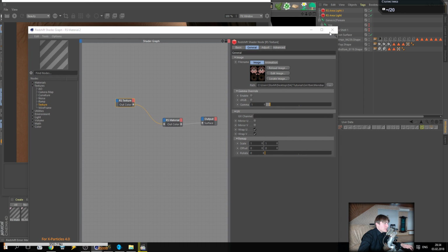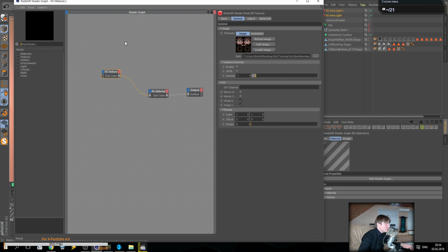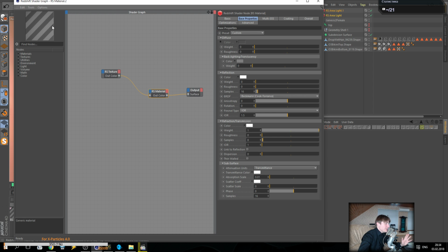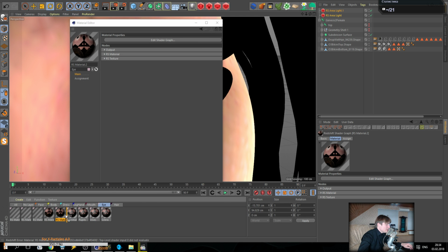it's still not ready. Why is it not ready? Come on. Ah, yeah. It's clear, it's not ready because I have full reflection. So just take out this reflection and apply a diffuse color up to maximum. Sorry, it's my mistake. For a moment, we need some reflection. Okay, now I'm ready. So take this material, copy, and overwrite our standard materials. Later, we will add some reflection.